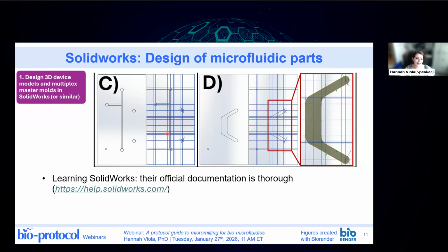It makes sense when you get in there and start trying to do things, but when you're trying to fabricate a part in SolidWorks, and let's say you only wanted to change this part and not the rest of it, you have to put in these reference planes so that you can say, I just want to move this plane up 2 inches, and then it moves the drawing for you and it does everything for you. And it also ensures that all of your circles are the same diameter, for example.